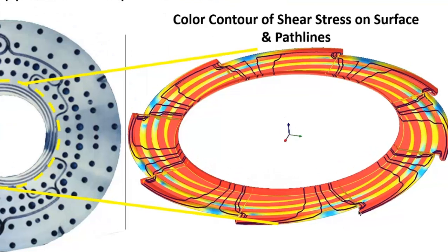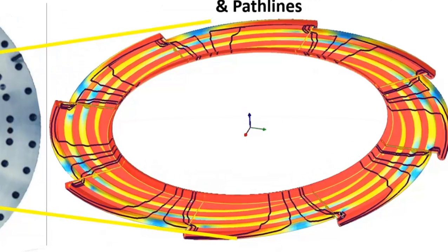And we can see once again that the geometry was not done correctly and that the path lines go up and back into the previous channel while some lines go along that channel and up. And right where we have the low stress regions, and you can see they're periodic all the way around, we have two flow fronts meet and we end up with these weld lines.